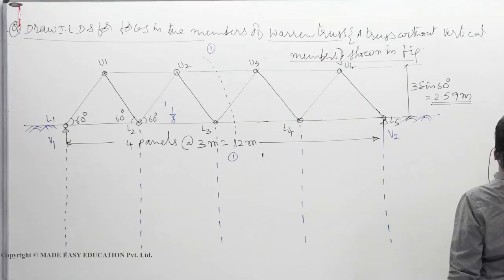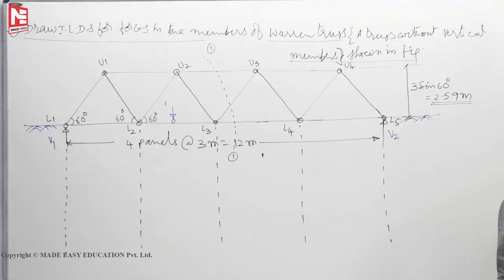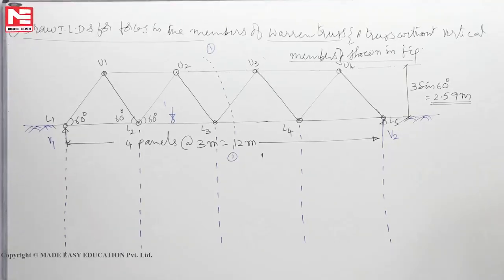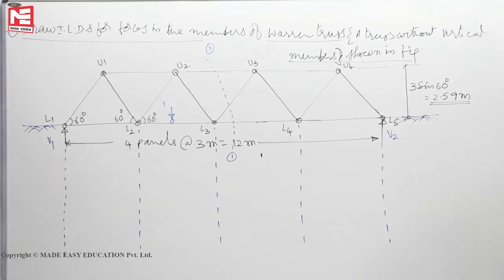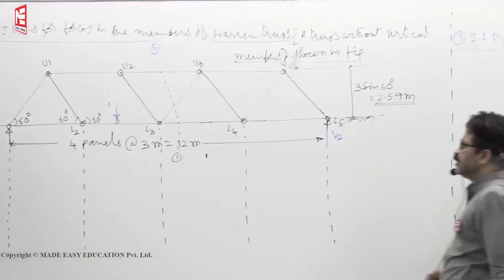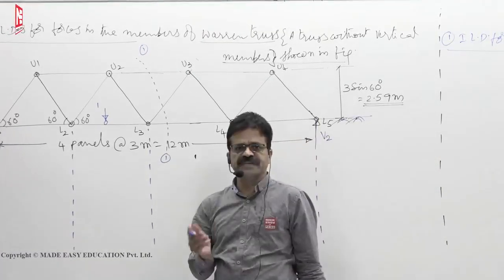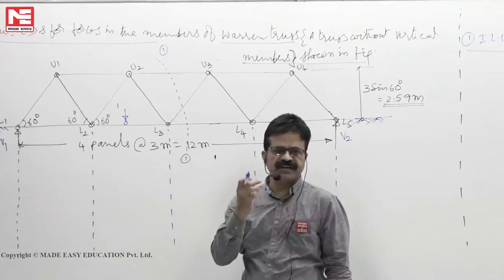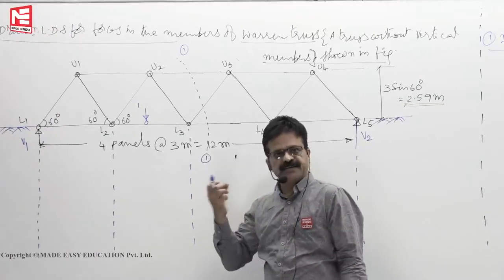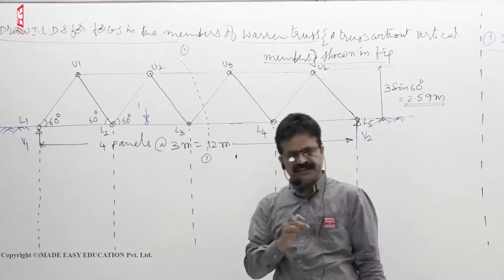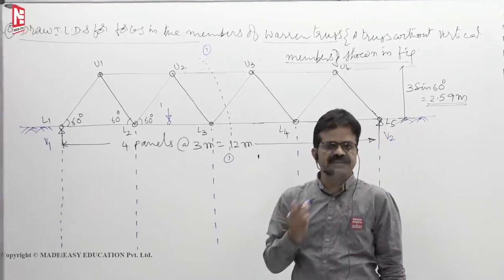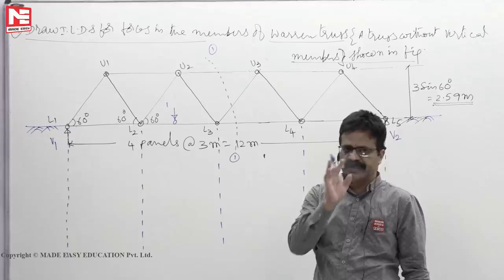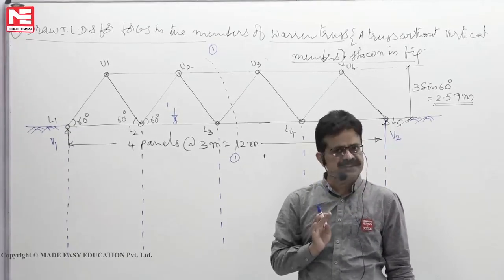We are taking now ILD for F L3 L4. Last class in the Pratt truss we have seen, let the load be between L1 and L3. Now look left side, draw expression. Now second case, load is on the right side. Now see left side, then find moment. That much story in the exam we should not take. Now you understood the process because we have taken 4 examples.